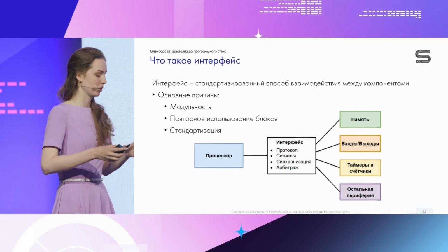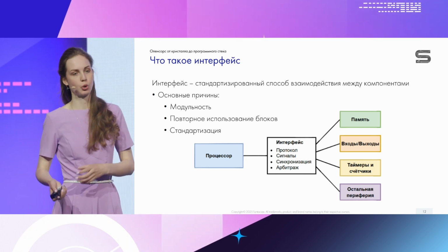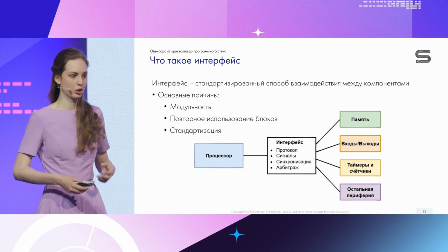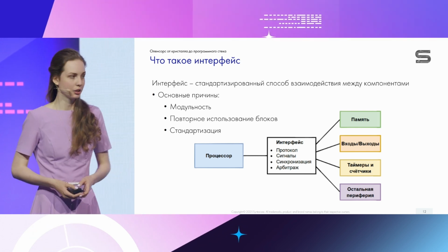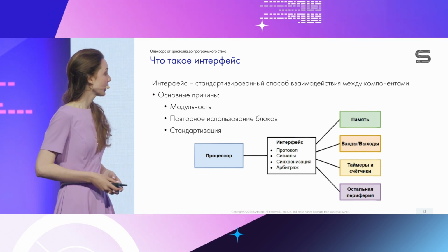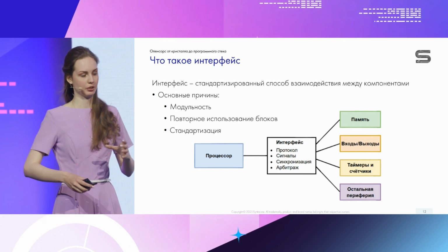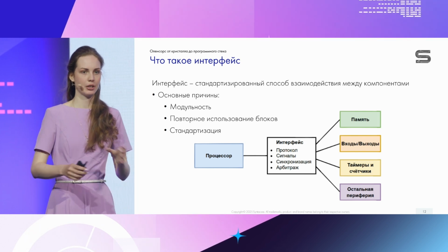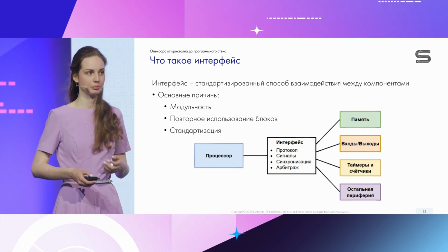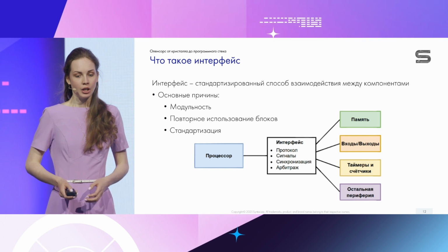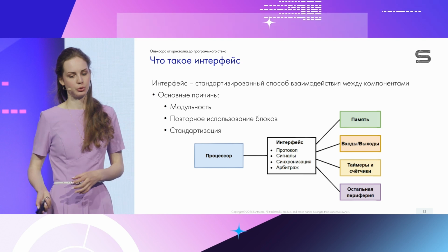So the interaction could be inside the core, between ALU block and register file, and also using interface there is interaction from outside of the core with memory or other periphery. A large advantage of the interface is that it is a module. So having written this interface once, we can reuse these blocks, and this approach is clear for many developers from inside. So to develop interfaces, we need some methodology.